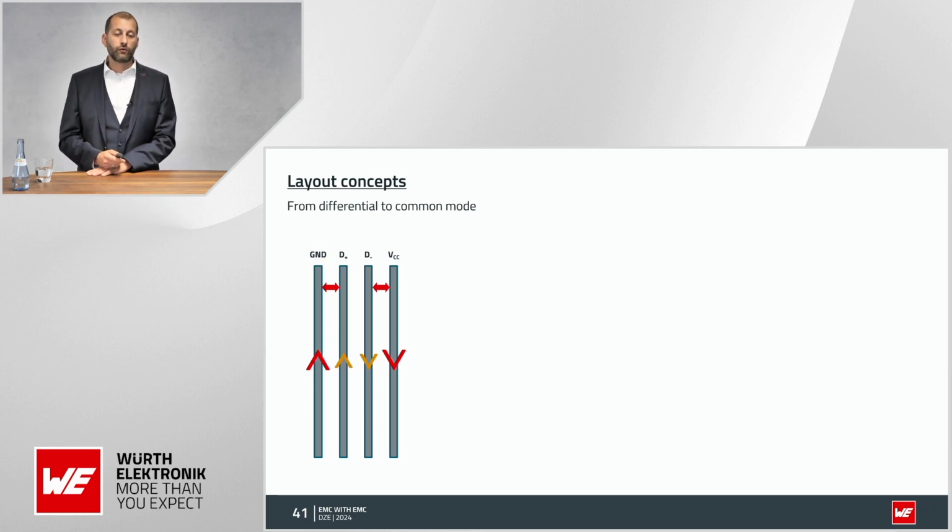If we would now apply, I don't know, an SMD ferrite, it would, of course, reduce the noise, but sometimes it will also affect your signal integrity, meaning the square wave is not ideal anymore and it's becoming rounded a lot. So what could you do?